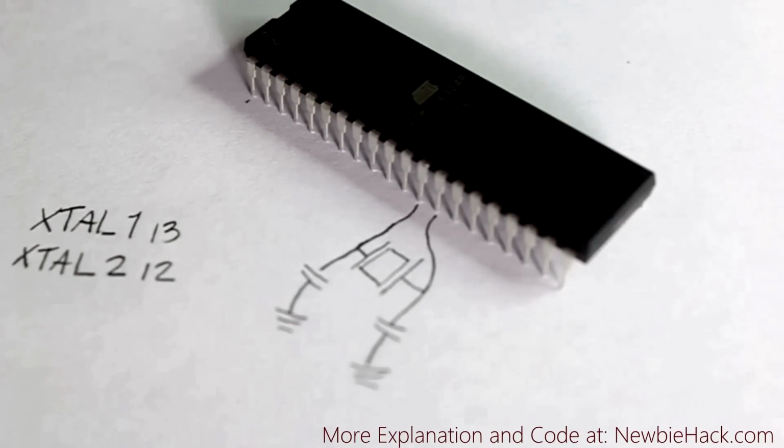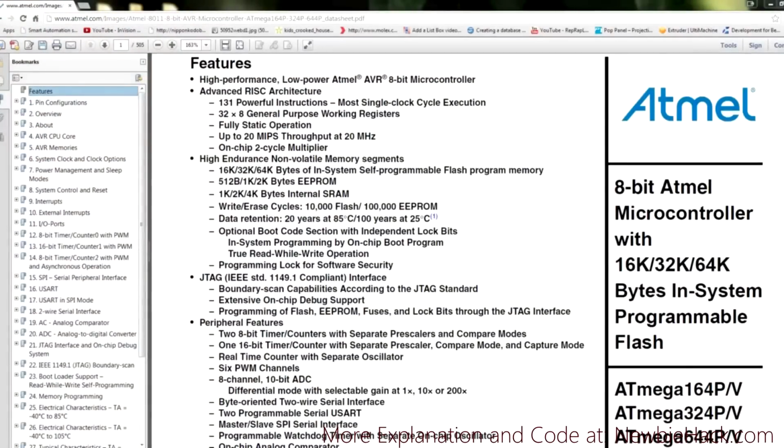Let's take a look at the data sheet and see if we can find a suitable crystal with the frequency we can use for communicating with the computer or a baud rate that we select. So let's take a look at the data sheet. If you don't know how to get to the data sheet, just go to Google and type in the part number and the word data sheet, and then you should have that in the first few results.